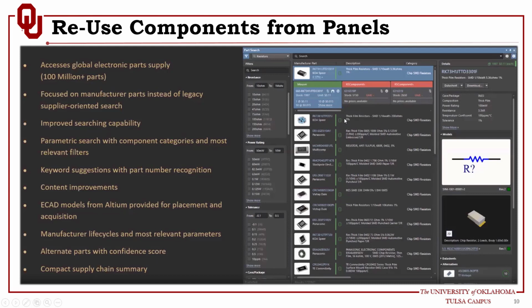And also, whenever one of these is updated by Altium, the software will tell you, oh, this component was updated. In order to generate the files, you need to update the component before you do that. The ERC and DRC engines in Altium Designer will give you an error, because you cannot compile the project if any of the components you are using from the managed-based library is not up to date. So you need to make sure they are up to date. Updating these components is just one click, etc.